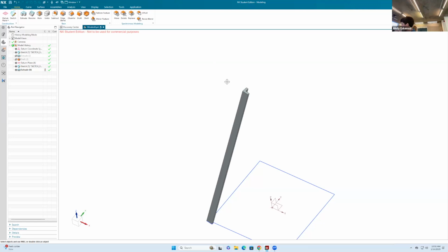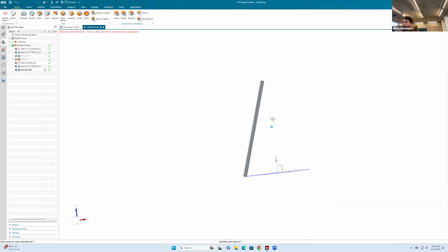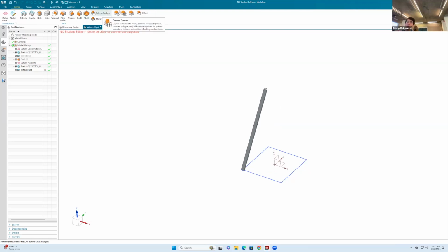Here's where the magic starts happening. So I'll do a little bit more. That way folks can then continue doing this with the structure. But now we'll go to our friend, the pattern. But we're going to use instead, there's different types of pattern. You can look them up here. There's one that's called body pattern, face pattern, feature pattern. We're going to use actually geometry pattern in this case.